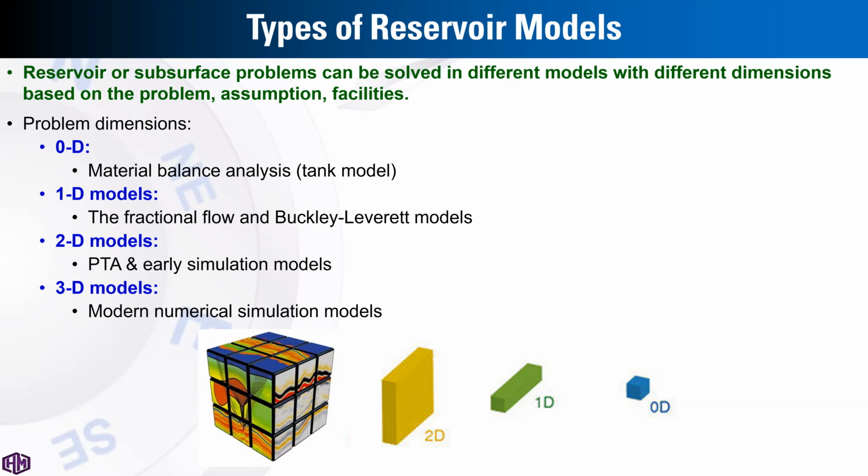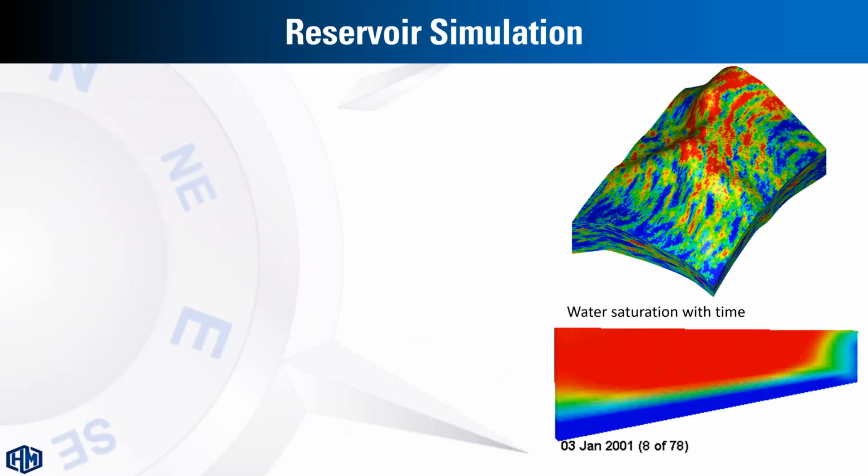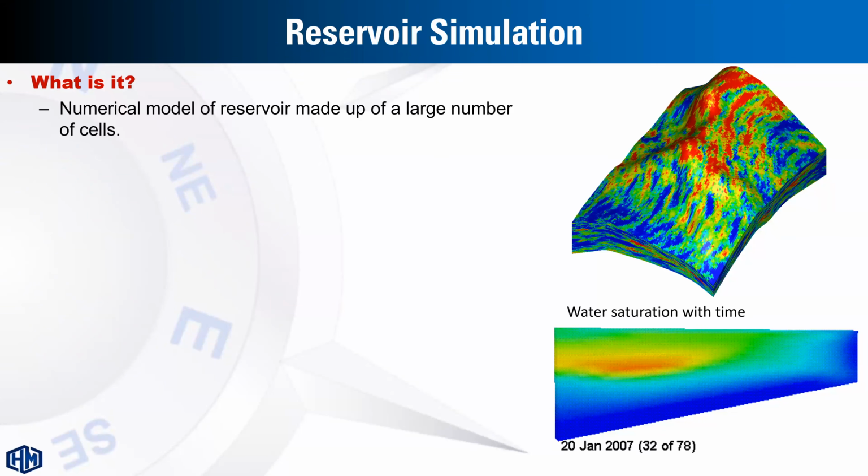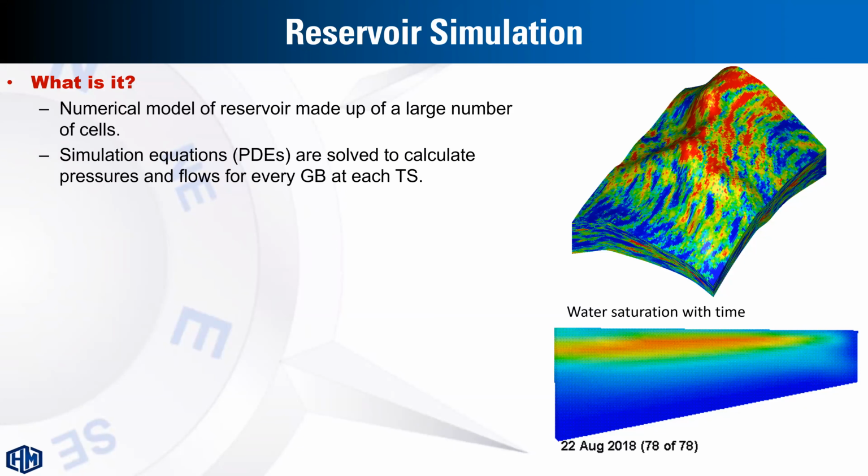So reservoir simulation is simply a numerical approach for reservoir characterization and performance evaluation, by subdividing the reservoir into a specific number of grid blocks or grid cells. The simulation equations, which are partial differential equations, are solved to calculate pressures and flow for every grid block at each time step for the simulator.